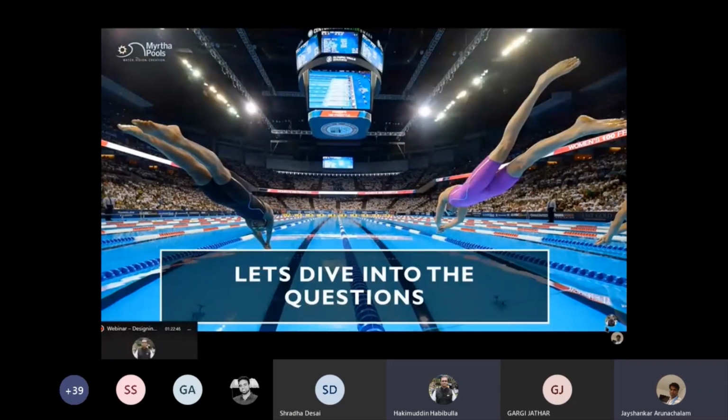So, we'll get into more detail when we're interpreting the FINA rules, but the minimum depth of 1.35 meters is purely based on the assumption that the FINA rules are meant for competent and competitive swimmers who know how to dive appropriately. So 1.35 is the minimum diving depth for that category. And the depth profile can then go down to 2 meters.